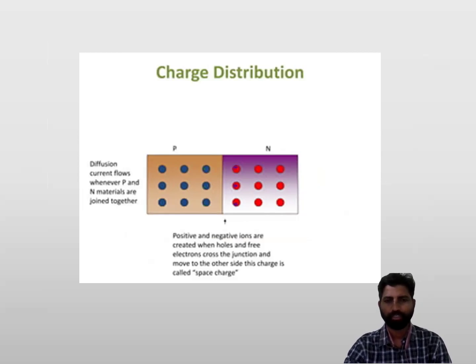In general, the P type material has majority carriers, which are an excess of charge carriers called holes, and in the N material the excess charge carriers are electrons. When these two semiconductor materials, with positive and negative ions, are placed together, by natural attraction the electrons, the majority charge carriers of N, will diffuse into the P type material.